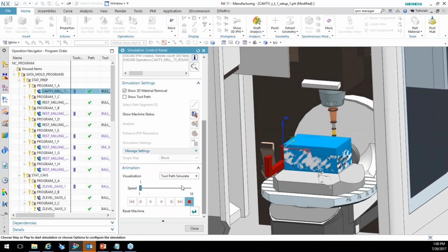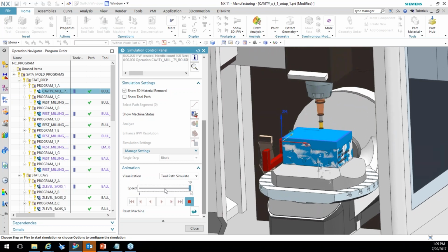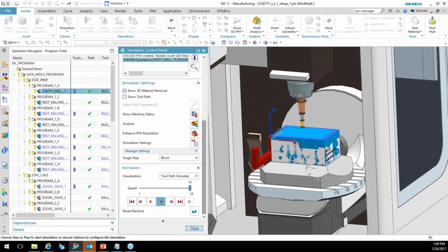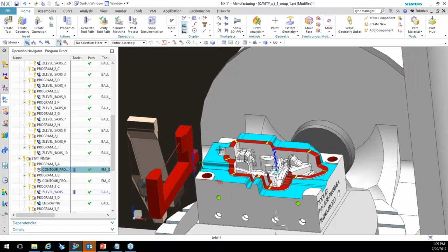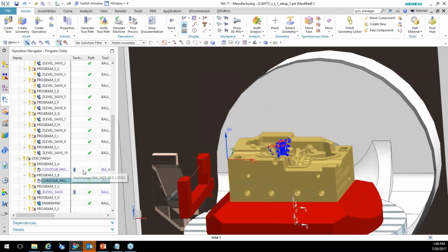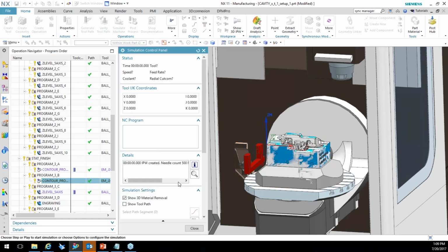Like that. As this cuts, it does show you all of the machine motion. It will show you the rotation axis and it will give you a full definition of what's going to happen in the machine tool. The only difference is it's not running off of G code itself. Let's go down here to that 5-axis operation. This is just another 5-axis operation. So now once I'm doing this, you'll see the full representation of the machine tool. And as I said, this is still toolpath simulation.